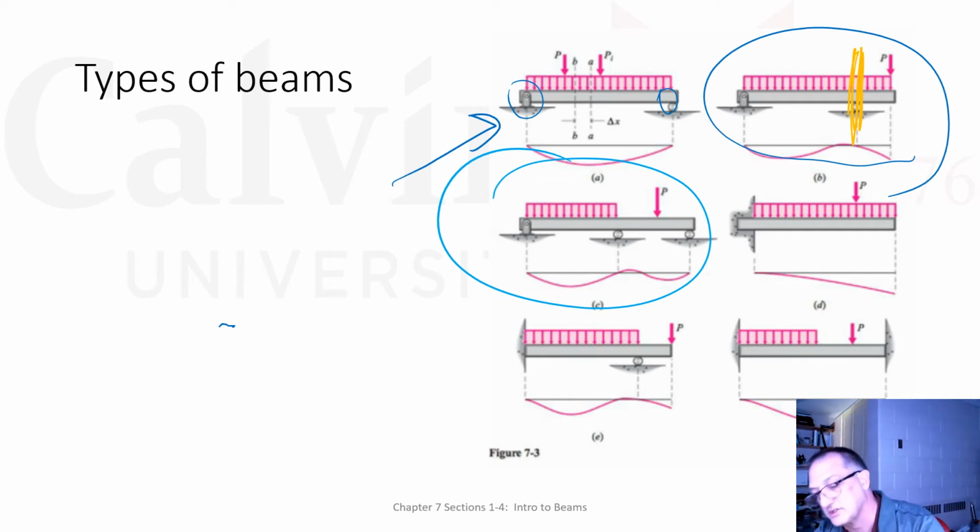I'm going to put a coordinate system on here. So there's my y, there's my x. I only get equations of force in the y. I can sum the forces in the y direction and sum the moments, but I don't get to use the x direction equation, because there are no forces in x. And so this problem is statically indeterminate. We'll have different ways of solving that in chapter 8.